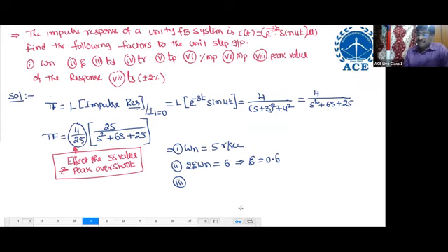Come on. 15 or 25? 9 plus 16, 25. You have written 15 wrong. Check it. Zeta 0.6. Very good. Next. Come on, delay time. You should solve. I should not solve, Guruji. Delay time, I have already written the formula many times: 1 plus 0.7 zeta by omega n. What is the answer? I think delay time is 0.284 seconds. Is it correct, Guruji? Check it.